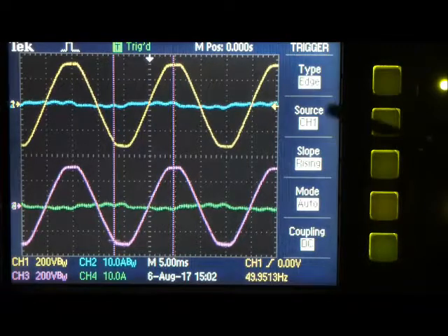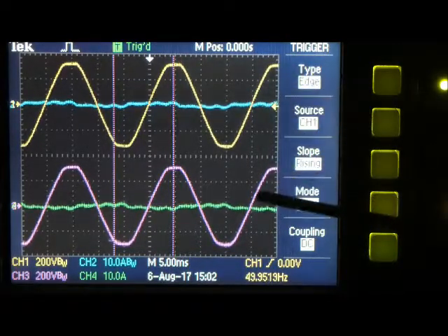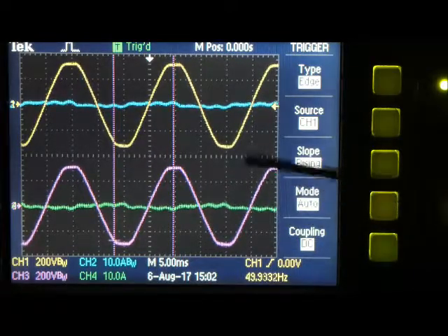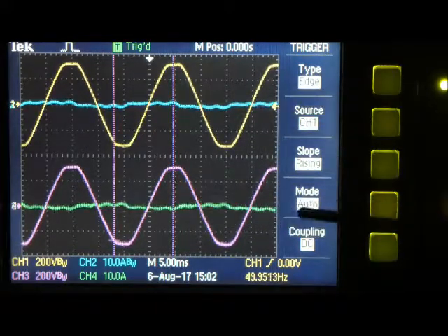And as the loads step down, for an instant current is fed back out to the grid, but the control loop very quickly turns the inverter output down so that there is again no current going out to the grid after a very short time. Now I'll turn on the PV generation.